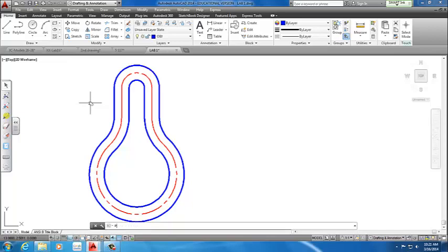So you type in pedit. If you see it on the board, where my command bar is, I'm typing in pedit. Another thing is that you do not have to select the command bar to type in things. All you have to do is just type it as is. You don't have to click down here to type stuff in your command bar. That's the old school way. This is the new school, which is 2008 and up, is just type it out. Saves you time.